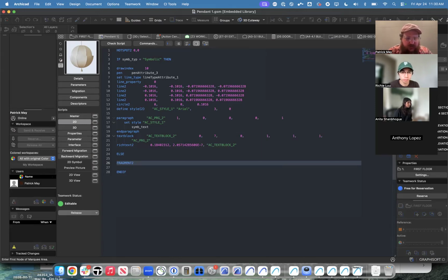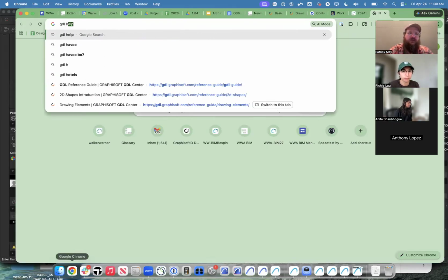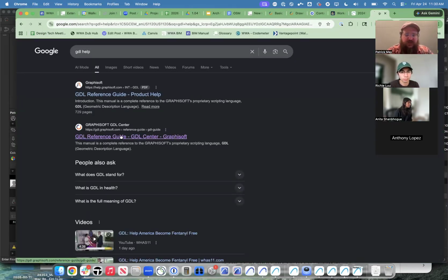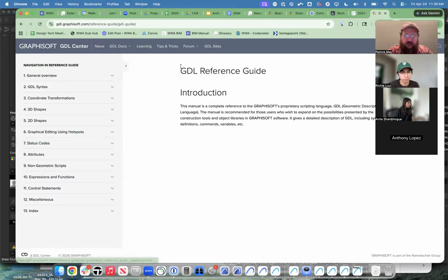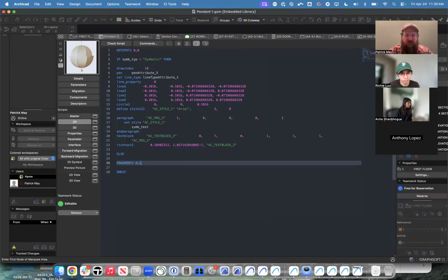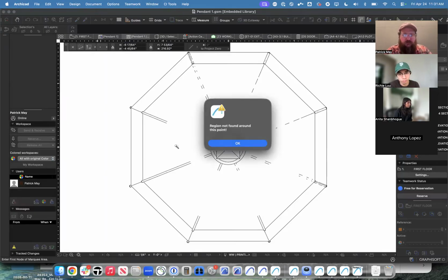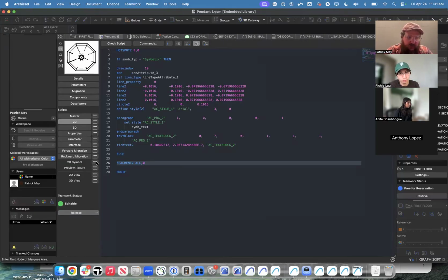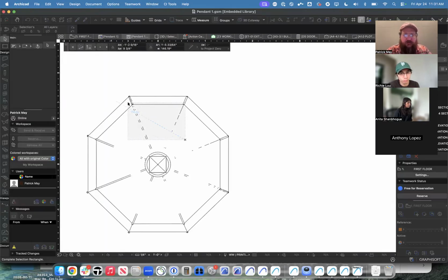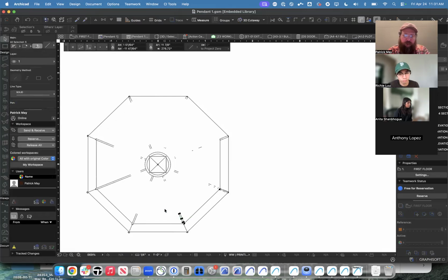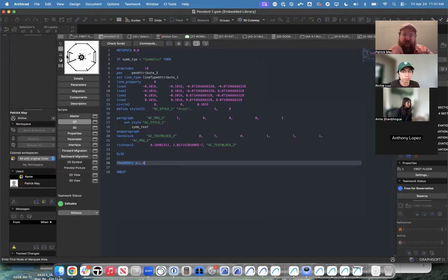What is the fragment command? Hold on just a second, let me pull that up here. I think it's all, comma, 0. Well, let's just check that. All comma 0, and then check the script. Yeah. So then instead of using the 2D view, it's going to have whatever I put here. So if I start cleaning a bunch of this stuff up, right, now my 2D symbol looks like that instead.